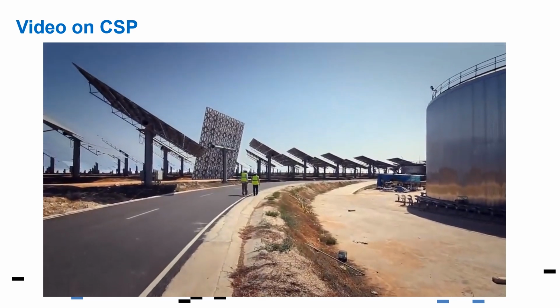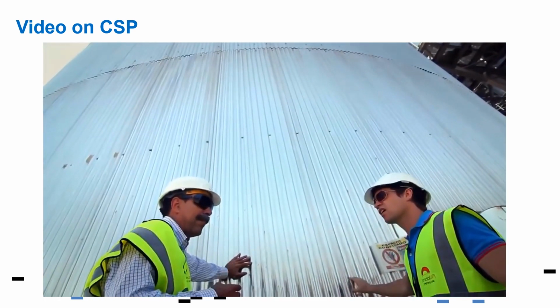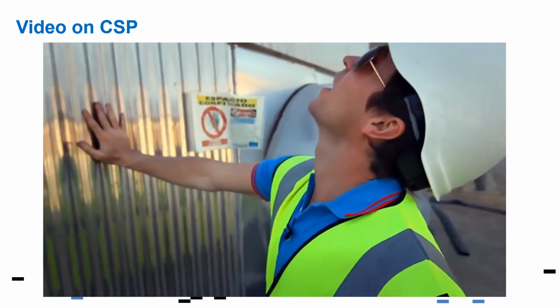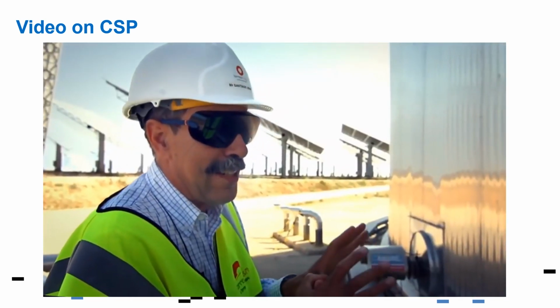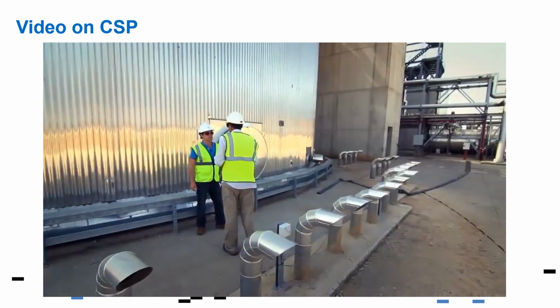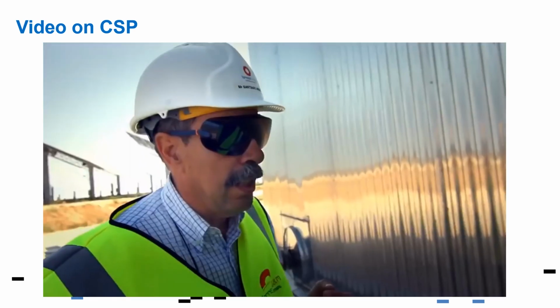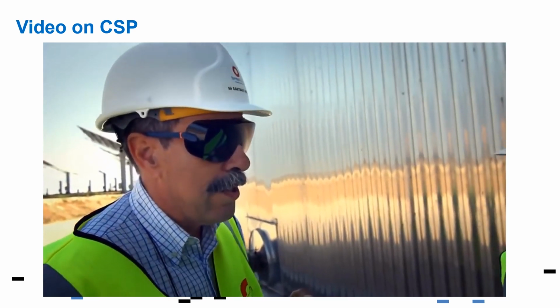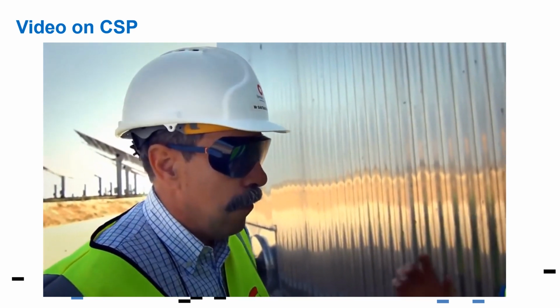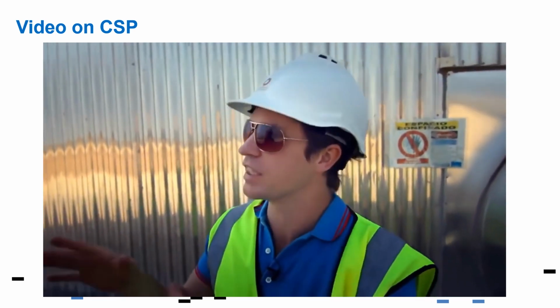This is the hot molten salt tank that contains the molten salts at 565 degrees. This is like a big battery, but it's a thermal battery. It's not an electrical battery. In fact, the energy which is accumulated here is enough to continue operating the turbine for 15 hours at full speed. So this is what distinguishes this place from other solar tower generators around the world. It's actually that storage. Exactly.